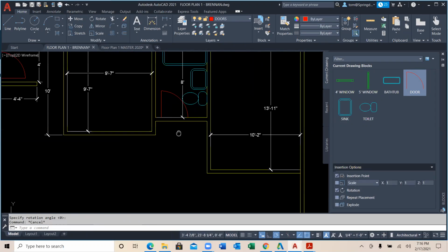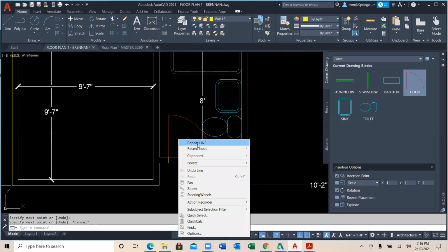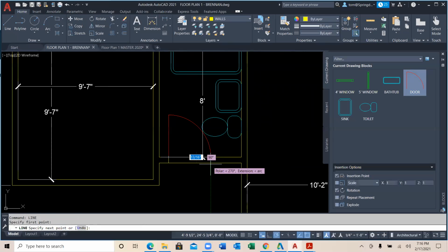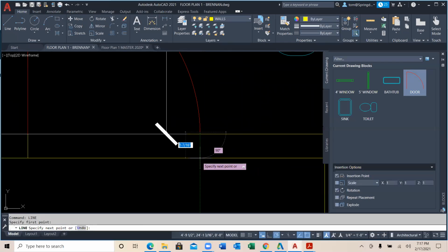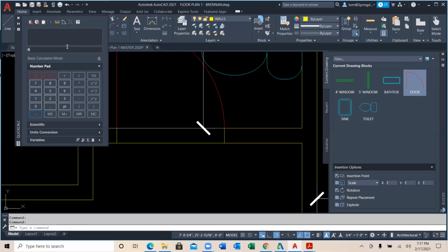And obviously using your adding and subtracting is going to help you in this whole thing. I don't want to give you every single dimension, because anytime you're working in AutoCAD, you're going to have to do some math in your head and so forth. One thing I will show you that's kind of cool here is AutoCAD has a tool that if you need to do a quick calculation here or there, there is a tool called Quick Calc, which is actually located right here. You see right there, I'm hovering my cursor over it and I click on it. When I click on it, it opens up this quick calculator right here.